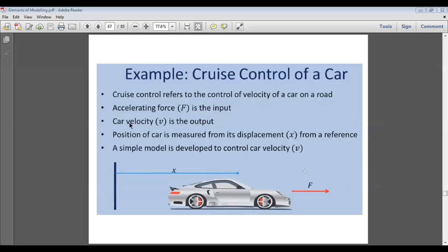The procedure is that you start with the simplification from the real, physical system to its equivalent structure. Then you make some simplifications. From that you identify the masses. Then you draw the free body diagram. And from the free body diagram, we write a mathematical equation using D'Alembert principle. Today we will see one more example so that you have clarity about what we are doing when we say mathematical representation of a mechanical system.